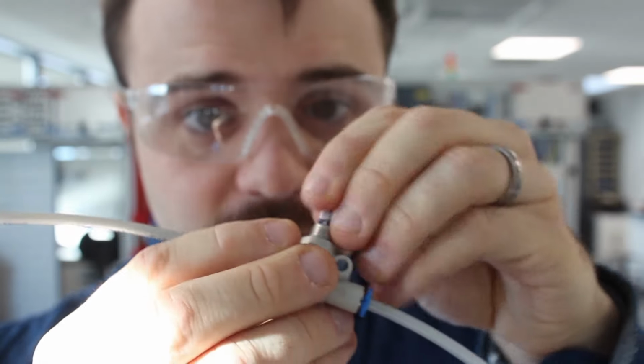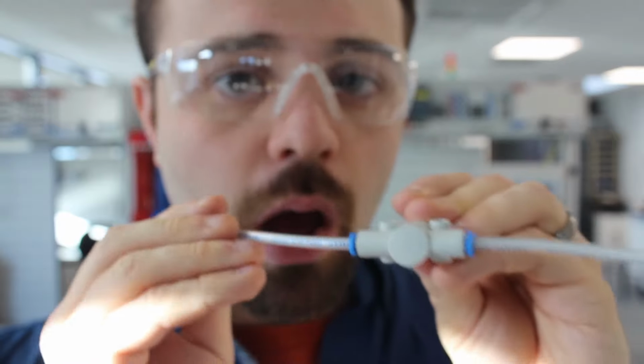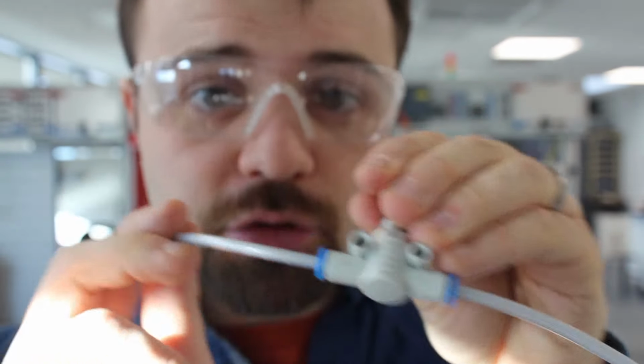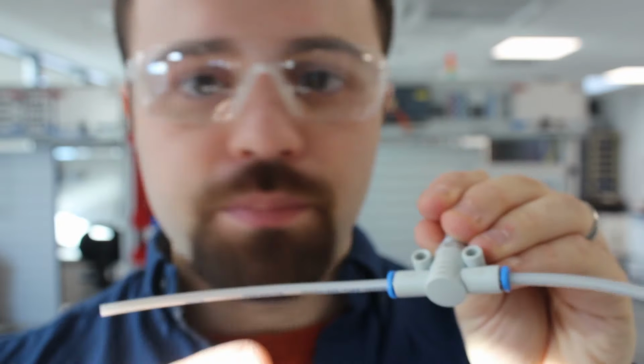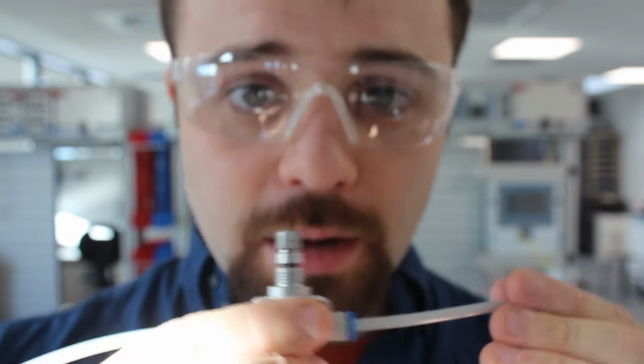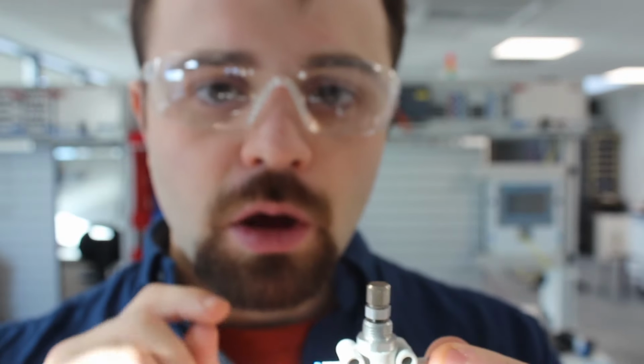If I restrict the valve right down, I'm then able to blow through only in one direction. So this way, the way that the arrows go, will be restricted. I can't blow through, but I should still be able to blow through the other way. And I can. So it's a one-way flow restrictor. We can use these to fit to the cylinders. That's what we're going to have a little look at now.